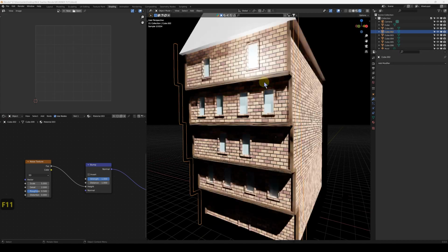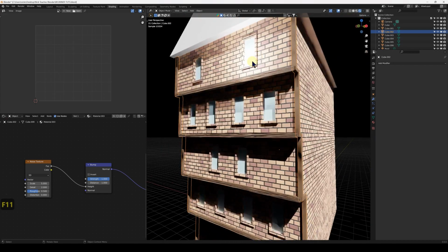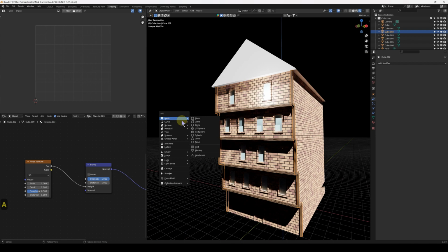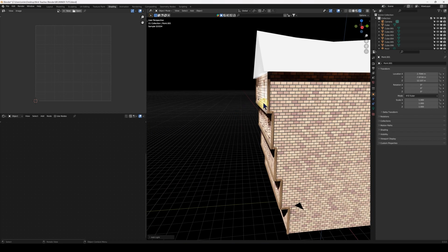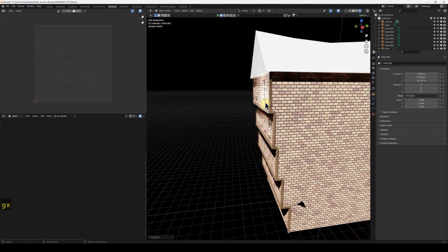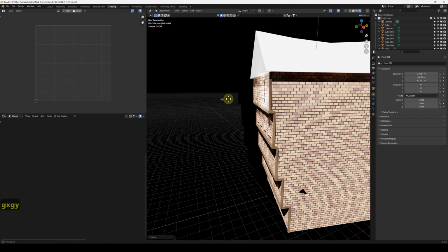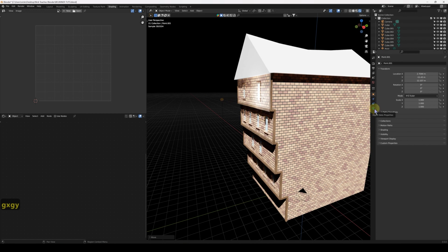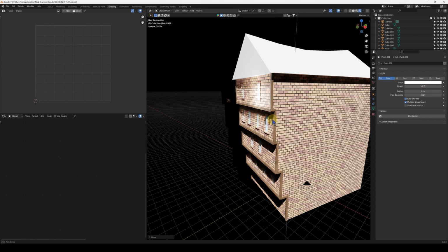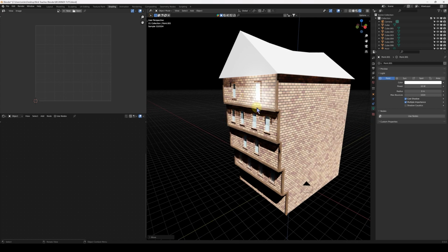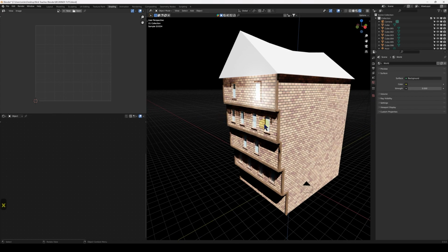And I realised I should have mentioned this just to help if you want one. To add a light, just press Shift A, and then you've got in this menu, light. And it will always arrive where your 3D cursor is, which apparently is here. So if I just move that on the Y-axis, there's the light. And then you can access the controls here under data properties, how much wattage, the radius, things like this. And then yeah, if you wanted to add another light like I did in the last one.